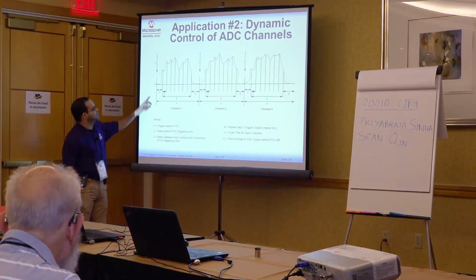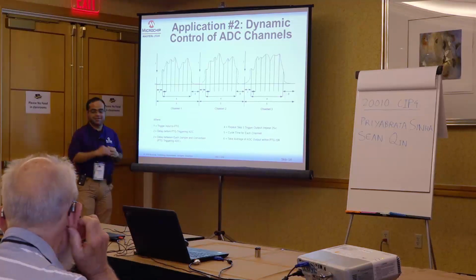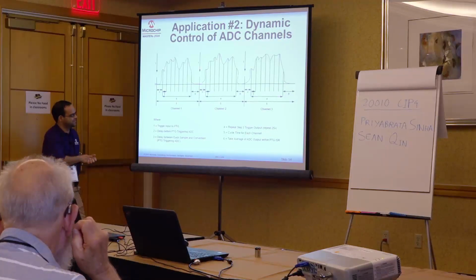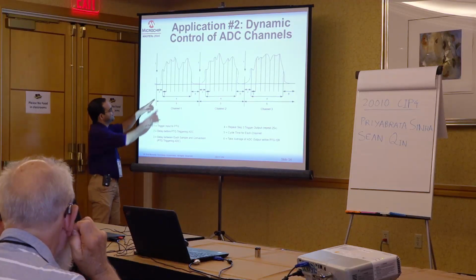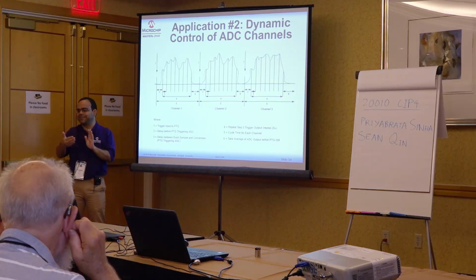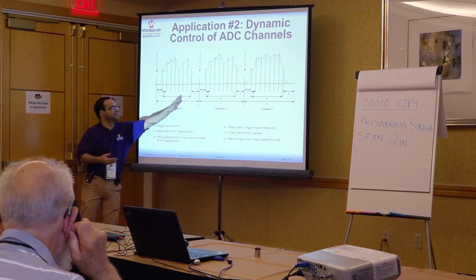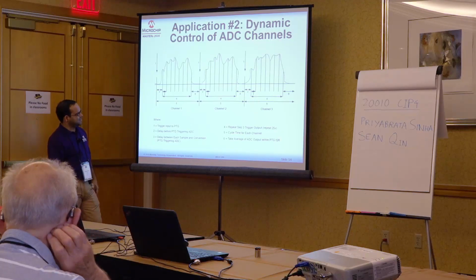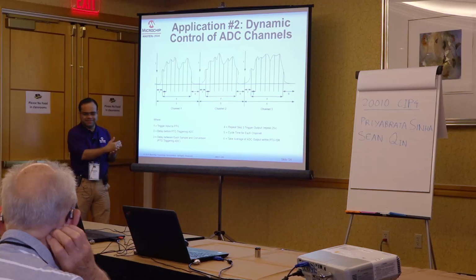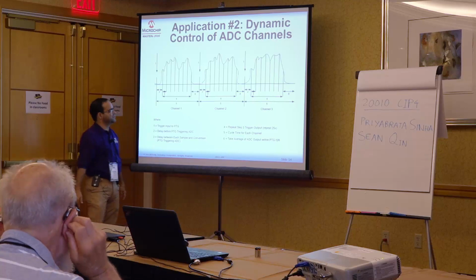And then the PTG imposes a certain delay, and only after that it sends a trigger to the ADC to sample that particular analog signal. And it needs to do that so many times, right, because it is taking multiple samples, and between each successive sample it again needs to have some delay that would determine what that conversion rate is basically. So there's a delay, there's an ADC sample request, there's another delay, another ADC sample request, and so on, and you specified how many times you want to sample it.